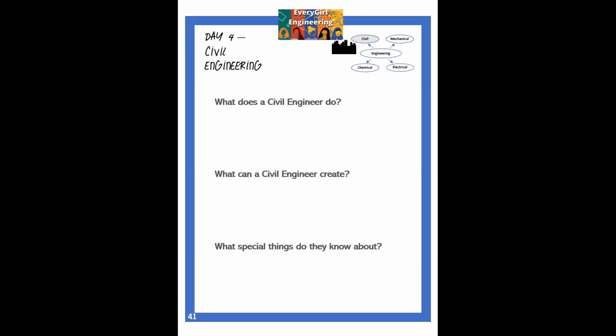So they work very closely together through the design. And then once it comes to construction, the architect's involved in approving submittals. A submittal is where, say, the drywall company is saying, these are the materials I want to use. Is this okay for me to install in the project? And I would review it the first time and say, yeah, I think that looks good. That looks like it meets the requirements.